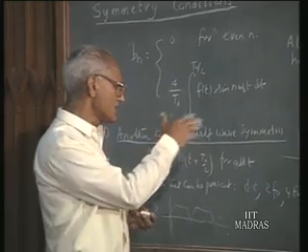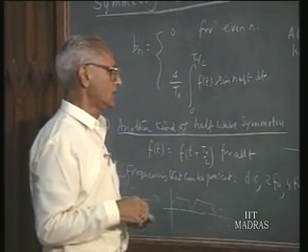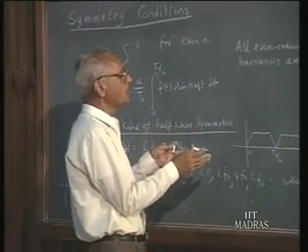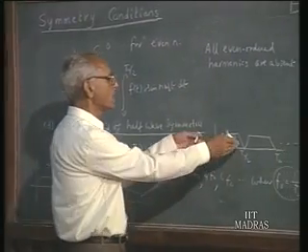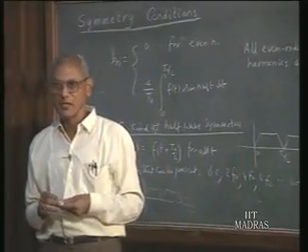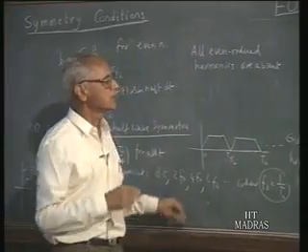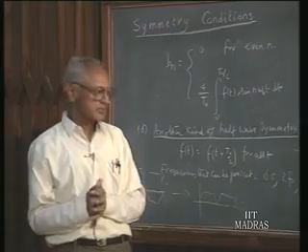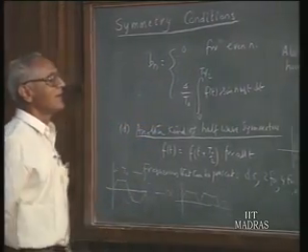So this is really a matter of definition. If you want to deal with this particular waveform on its own without reference to any other waveform, certainly it is permissible for us to call this the basic period and then analyze this in the conventional manner. But if you call this the period for this waveform, then we can say that only the even ordered harmonics are present. These are the 4 important kinds of symmetry that one deals with.